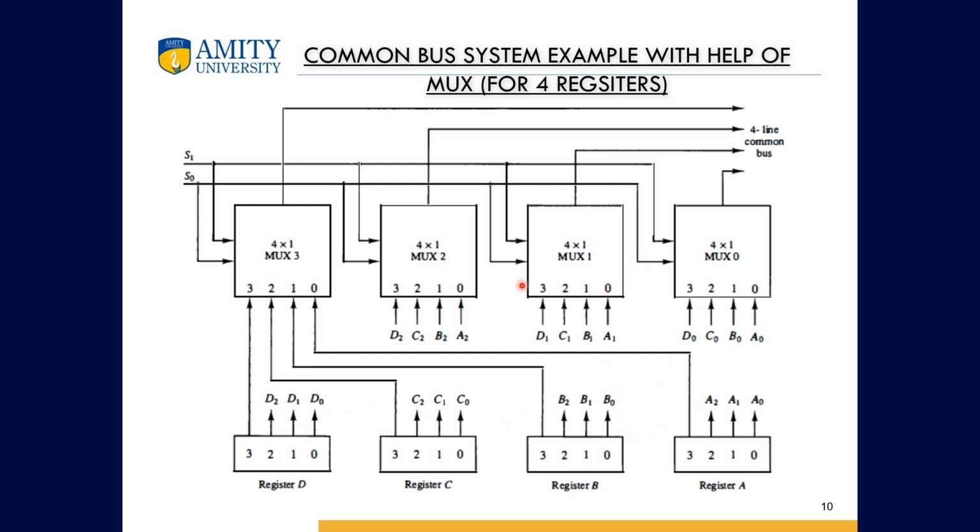One will have the first bit, and so on. These selection lines help us choose for the mux. So if both selection lines are 0, then the 0th bit will be transferred from each mux. Since we have common selection lines for each mux, 0 will transfer to the output 0 0 0. Thus, for 0 0 selection lines, the A register will be transferred in each mux. When A is transferred, the common bus line output will have A as the output.